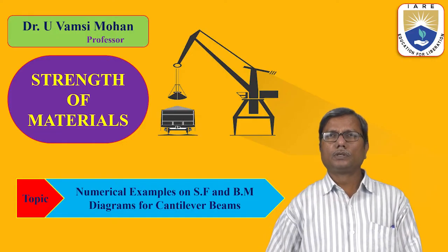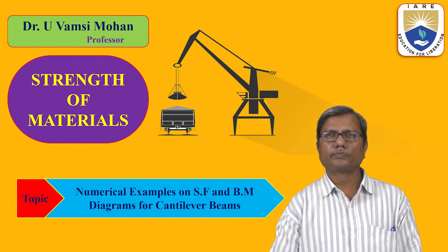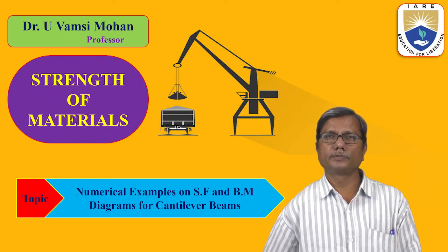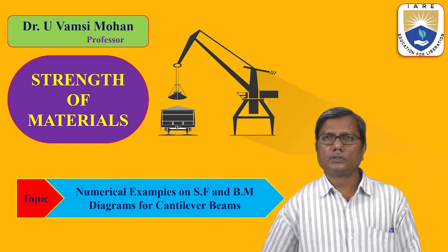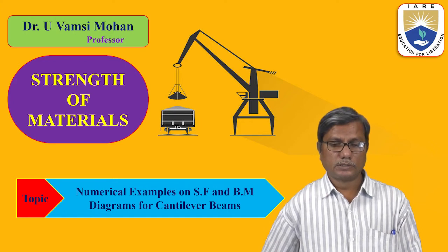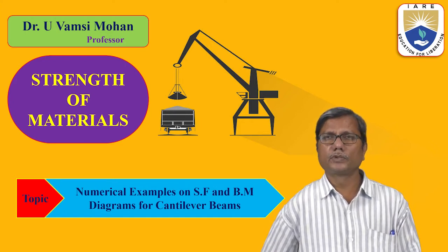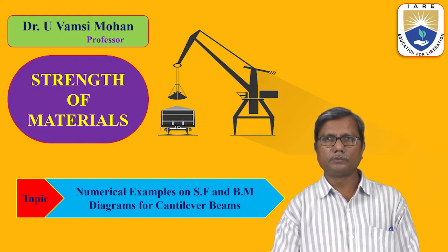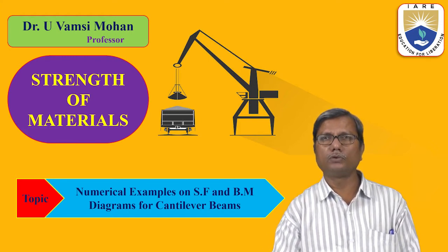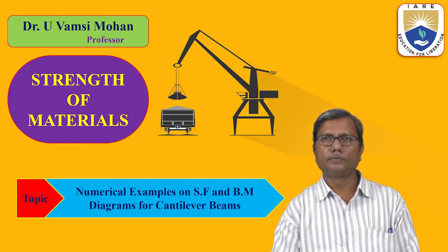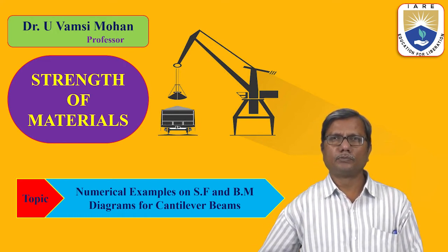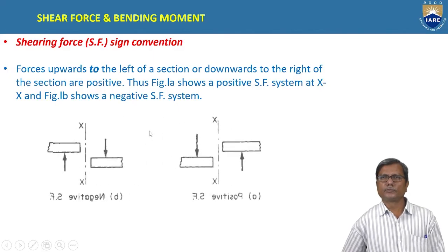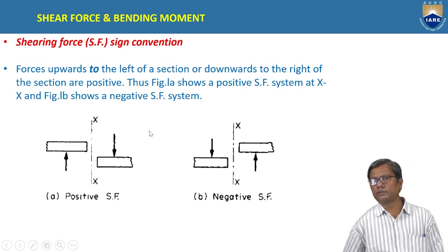In this session, we will be discussing the shear force and bending moment diagrams for cantilever beams with various load cases such as point loads, uniformly distributed loads, uniformly varying loads, and moment couple. So like this, we'll see the cases one after the other.